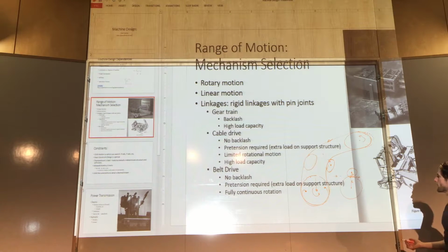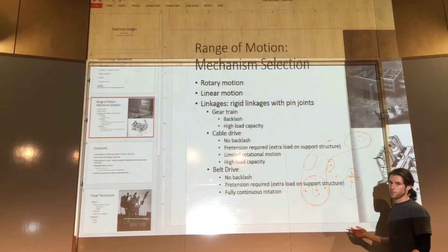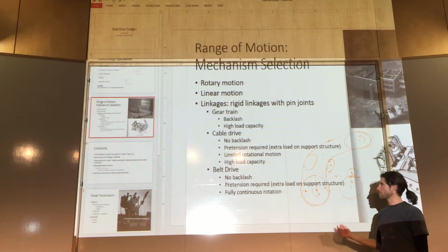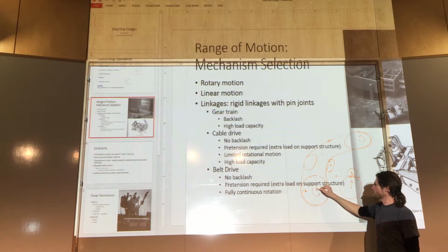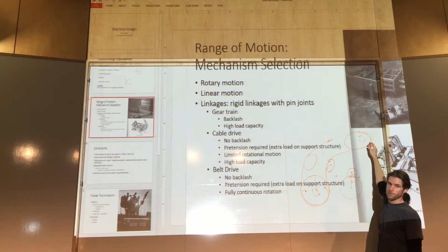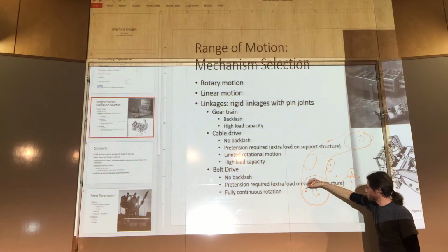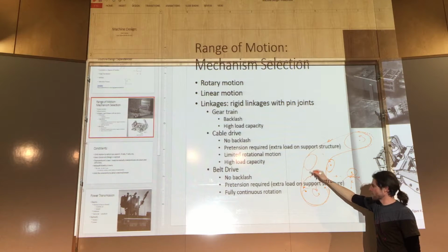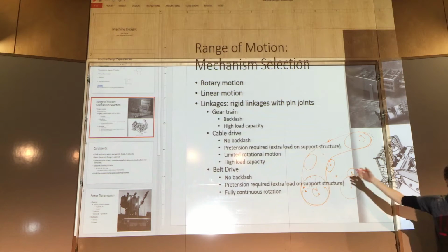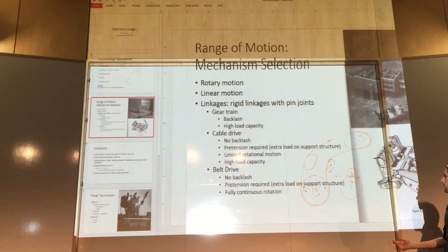So the problem with that is, well, maybe that's not so bad if that's what you have to do, but because you're putting this pre-tension on, say I want to put, I don't know, 50 Newton meters of torque on the end of there, and I've got some radial distance here, I've got some tension that I need to put on there. Might be 1,000 newtons or something like that, 250 pounds.